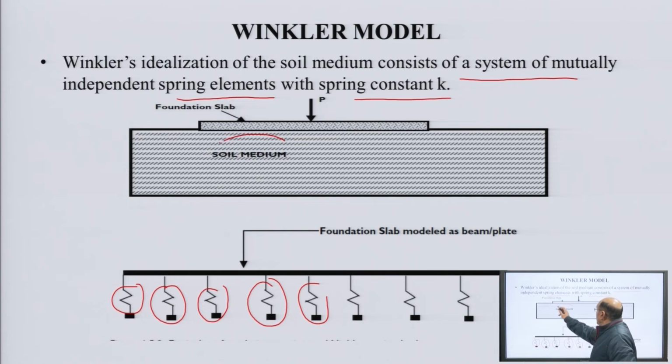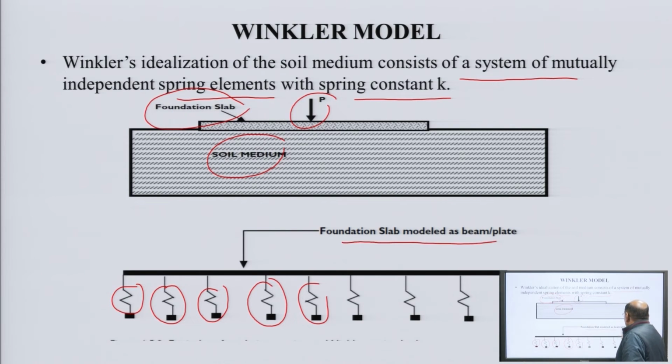This is the soil media, and in Winkler's model, the soil media is replaced by the springs having a constant k. So, the load is applied here and this is the foundation slab modeled as a beam and a plate. So, this is the basic of Winkler's model.